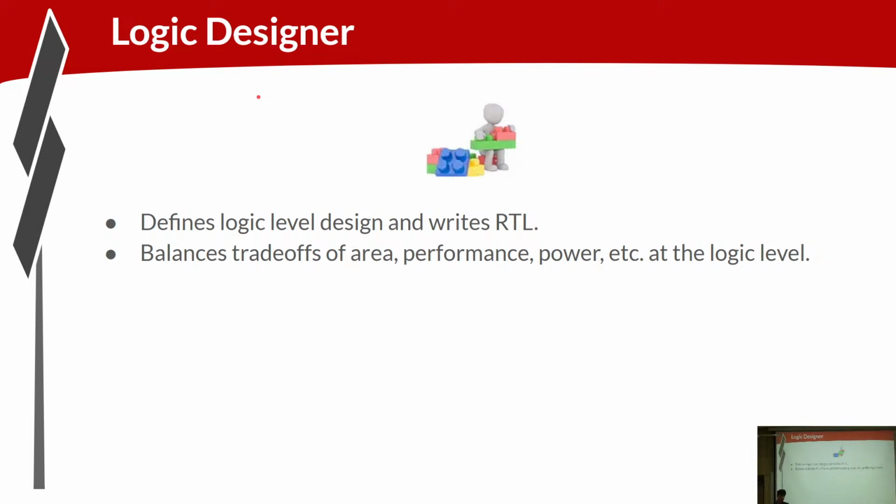The logic designer's role is simple. That's what you were in this course. The logic designer has one responsibility, and that's delivering RTL. But to do that, you're balancing all the trade-offs: area, performance, power. People talked about this term PPA. It's power, performance, area. Those generally are the three main characteristics of the silicon that you tend to be focused on optimizing. Certainly not the only ones. So, focused at the RTL at the logic level.